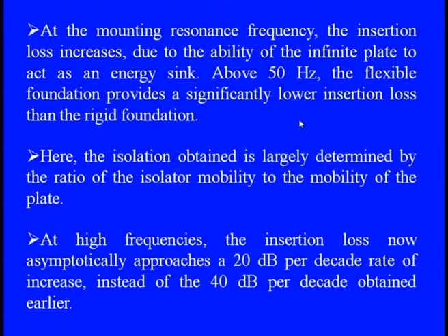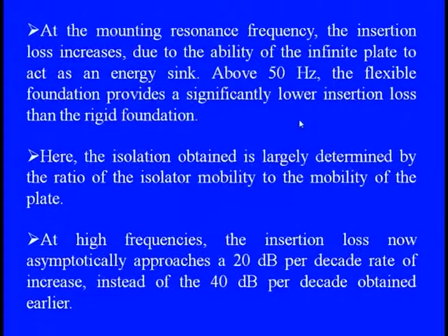But above 50 hertz, the flexible foundation always provides a significant effect with lower insertion losses, because we know that when we go beyond that, the absorption feature is quite significant as compared to the rigid foundation. Hence the isolation obtained is mainly determined by the ratio of isolator mobility to the mobility of the plate.